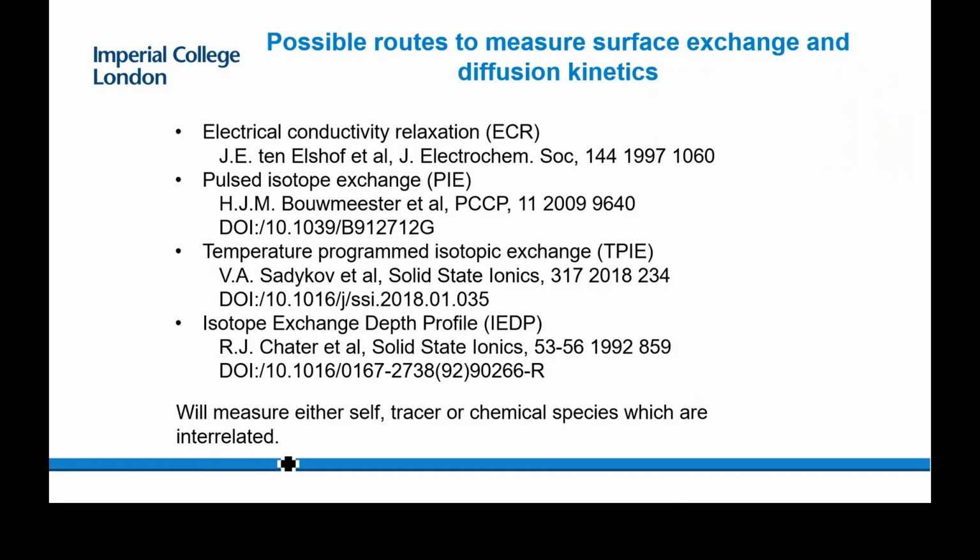So you have to be very careful in comparing diffusivities, whether you're comparing chemical diffusion, where obviously you have a chemical process, so you have a driving force across, you have a chemical potential, whereas in tracer and self-diffusion, you don't have that chemical driving force, you don't have a chemical potential. So the two are linked, but they're not absolutely directly related.